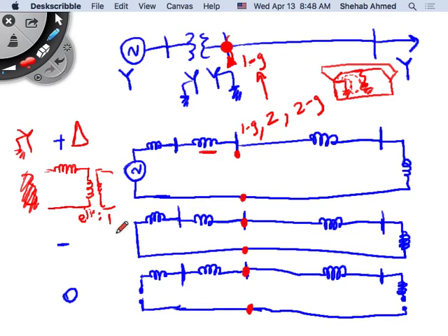How about negative sequence? Series impedance, ideal transformer, but we have to flip the e to the j30th, right? Negative sequence, remember we're flipping the e to the j30th? Go back, review transformers, review chapter 3. We were flipping the phase shift for the negative sequence. If you apply negative sequence, we did that in an example in class.